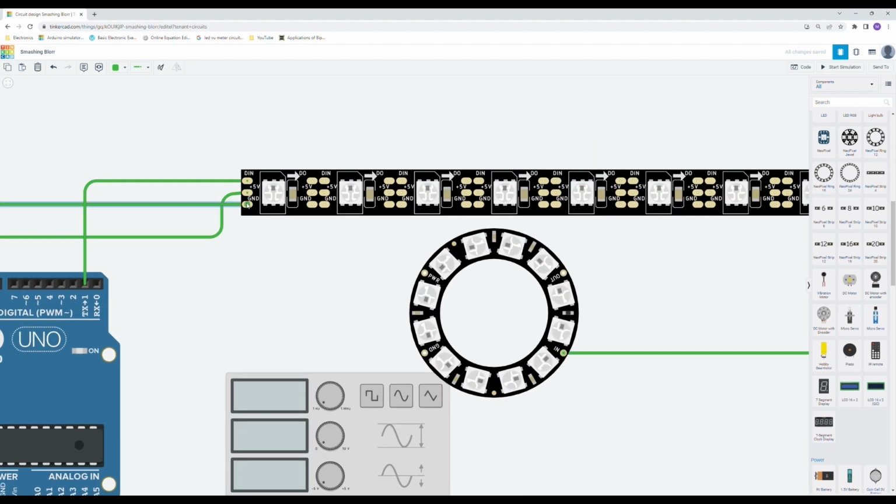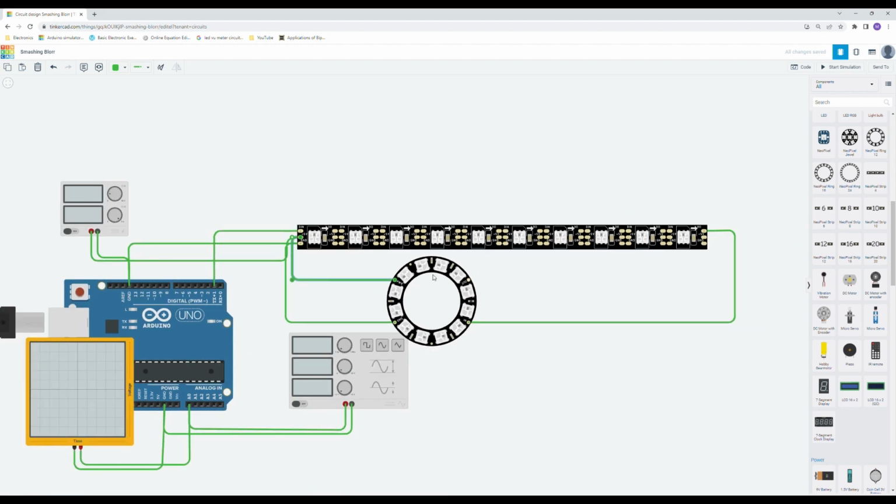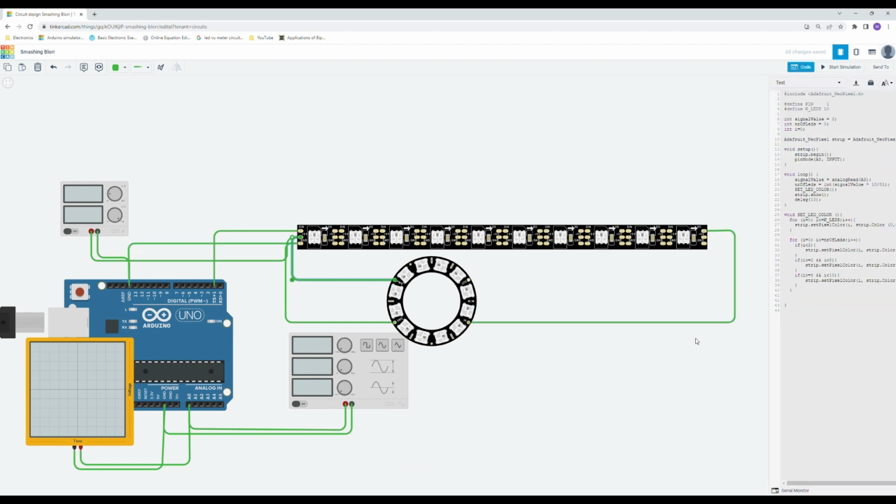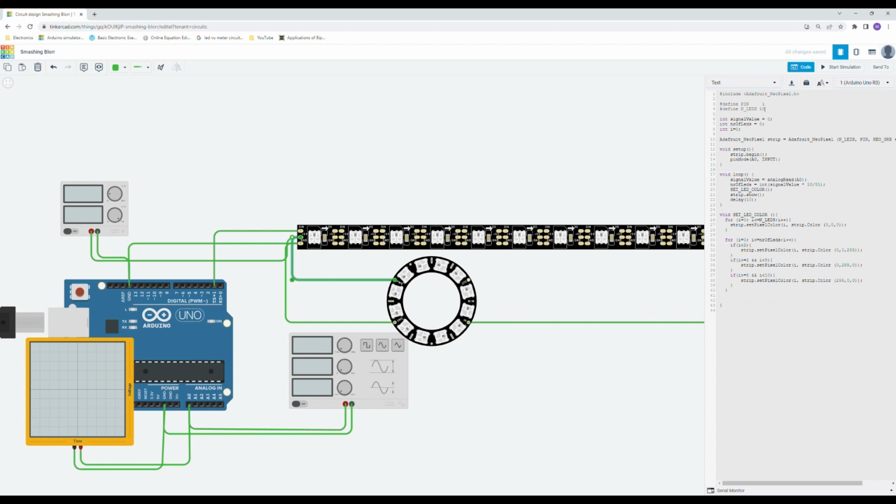I'm going to take the ground from this pin, so ground from our already available LED strip, so ground, and power also from here. And now, based on this configuration, you can put as many strips and rings and lights, just that you collect the data out from one LED strip to the other one so that they are serialized. This could make, yeah, kind of all the difference.